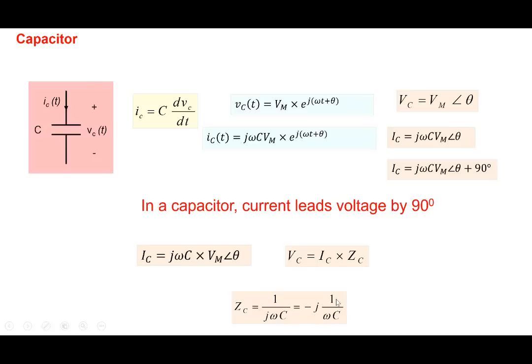So the idea is, again, the phasor relationship between a voltage and a current across a capacitor is related through an Ohm's law like relationship, where the capacitor is replaced by an impedance equal to 1 by j omega c. So you can see the advantage of doing phasor analysis: the relationship between current and voltage is a derivative, the derivative is now gone and is replaced by an Ohm's law like relationship, a complex number. So the replacement of a derivative or an integral by a complex number is the advantage that we get in phasor analysis. It makes the whole analysis simpler, as we'll see.